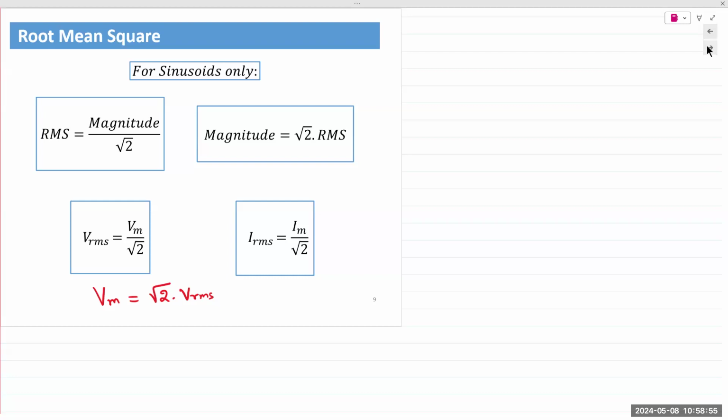What is the voltage that comes out of our power outlet? RMS value describes only one value. Peak just describes one instant in time, but it doesn't describe all values. Power outlet, we say 120 volts. Yes, it's RMS. All meters, all measurements are always done in RMS. Unless it explicitly states it's peak, it's always RMS. So 120 volts RMS. Got about a minute left.